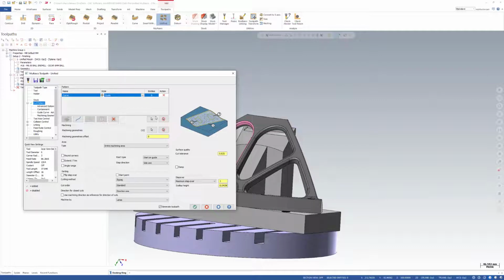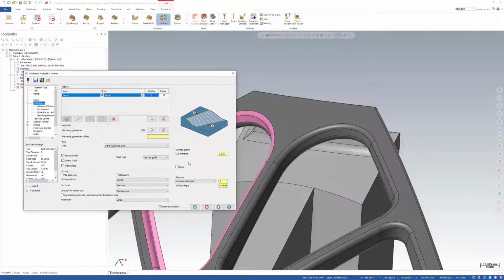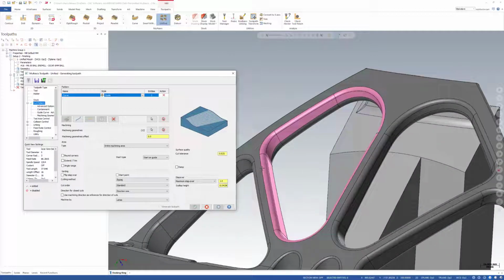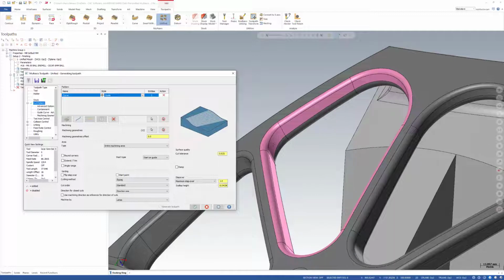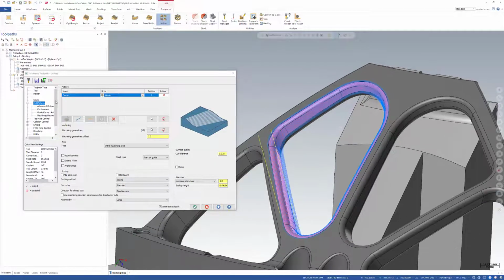So instead, let's do guide. With guide inputs, if I shift click there and shift click there in one session, I get, if I click preview, basically the same toolpath. This is going to be Morph style, so you'll see some areas will have a tighter step over, some areas will be looser, but that's just because we're morphing from one edge to the other.